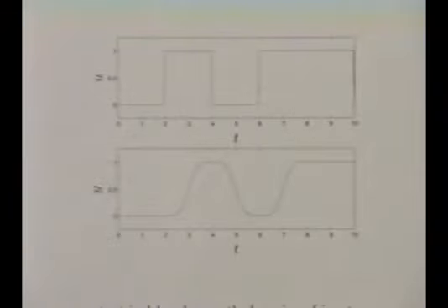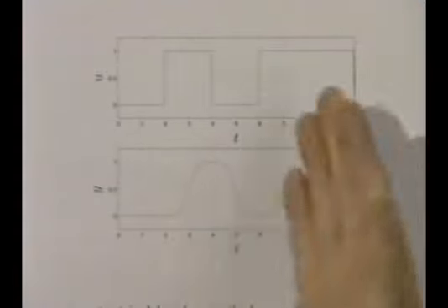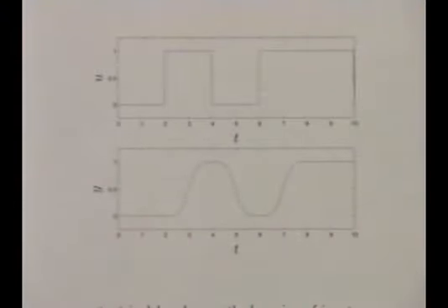Now, if you were doing communications engineering, the point here is that the output signal that comes out the other end of the wire does not look exactly like the input signal. But it hasn't been messed up enough to destroy your ability to distinguish ones and zeros. Intuitively, and in later classes, you'll study this in far more detail. This signaling scheme with this cable and this impulse response clearly is going to work. We can make a detector that will tell you whether a 1 or 0 was transmitted.